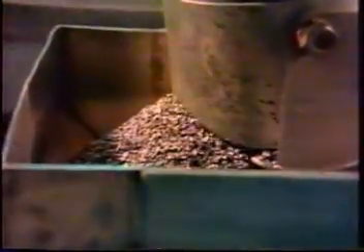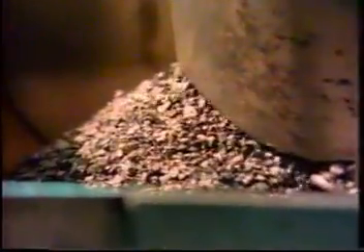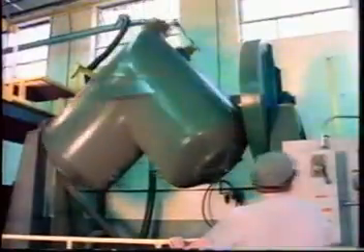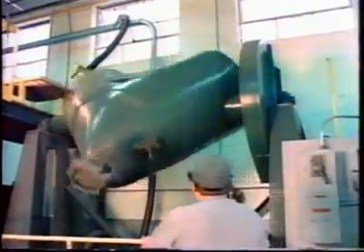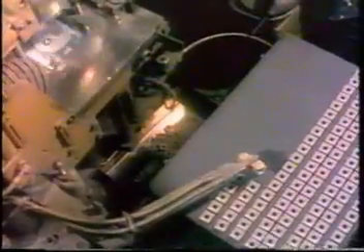The crushed and separated ore is then further refined and converted to tungsten carbide powder with a consistency close to that of talcum. The powder is then combined and mixed with various additives. These additives give the tungsten carbide the desired properties required for differing uses. The additives also make it possible to form the powder, making it easier to handle and converting it into solid shapes.